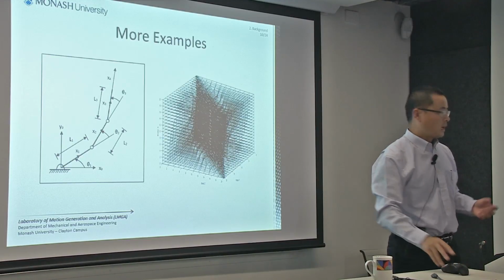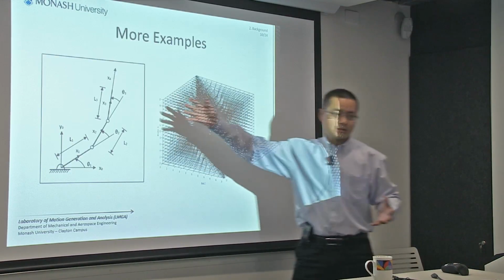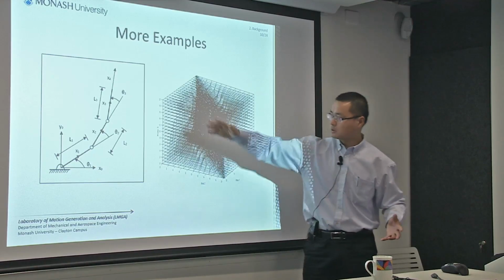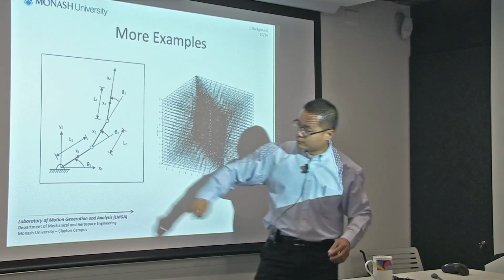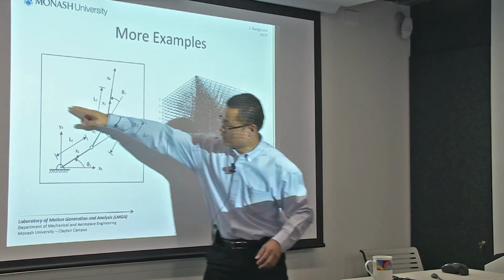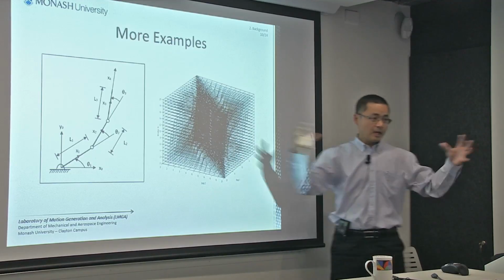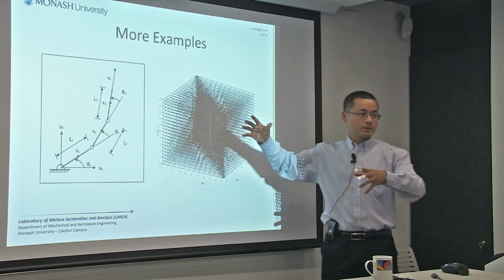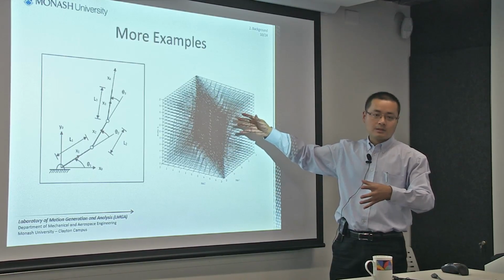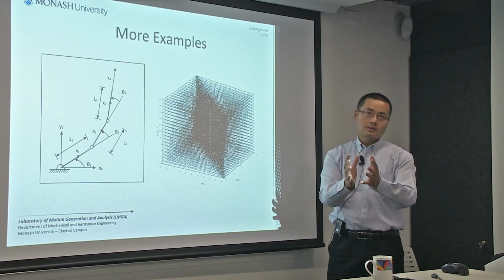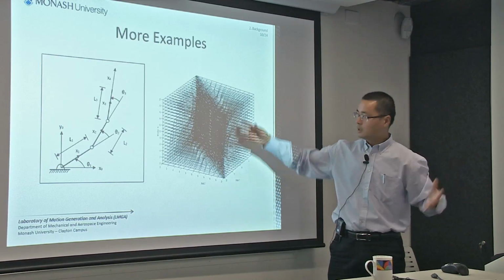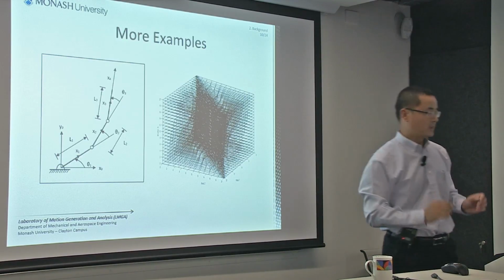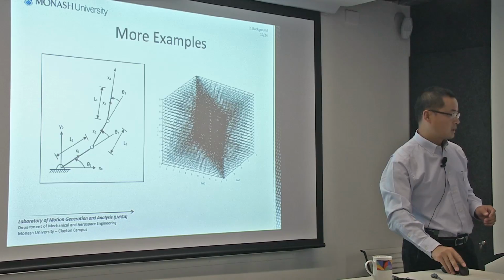We can also apply this to a robotic manipulator with three joints, 3 degrees of freedom: theta 1, theta 2, theta 3. I put one obstacle here, one obstacle here, one obstacle here. These obstacles are mapped into some strange shapes in this configuration space. Then I compress or distort this space, and create what I would call an obstacle-free configuration space. Then the path planning was conducted correctly.